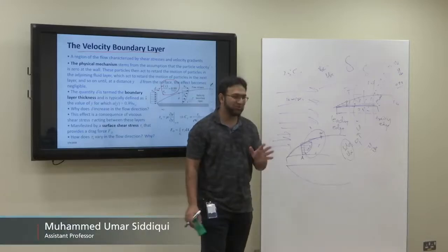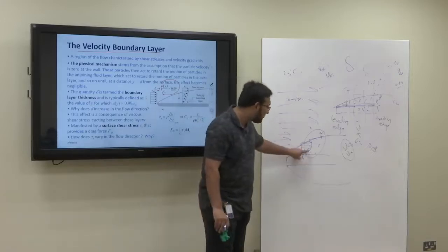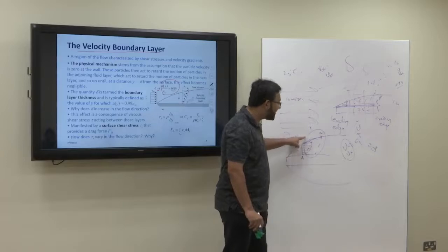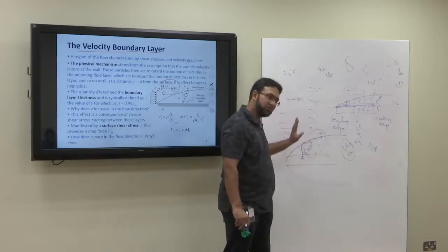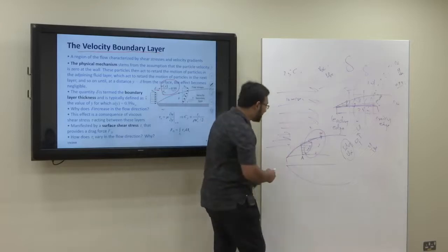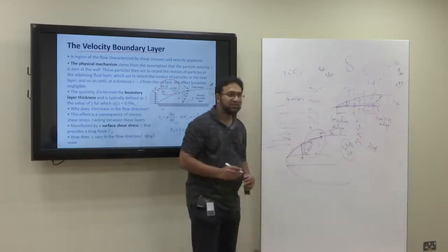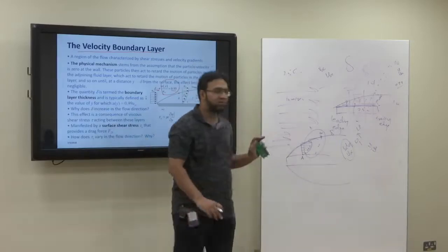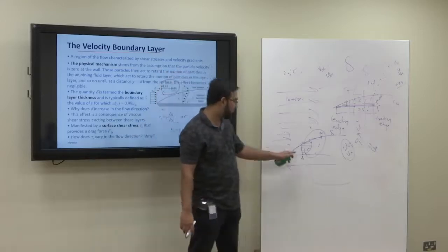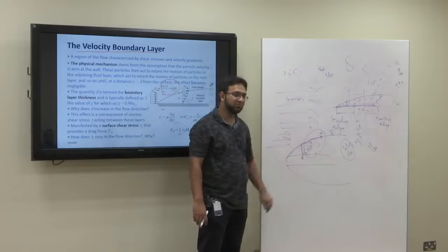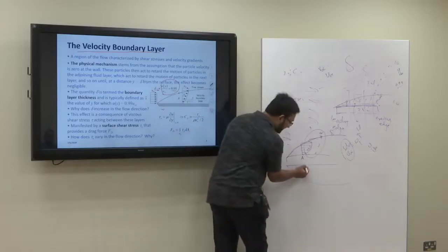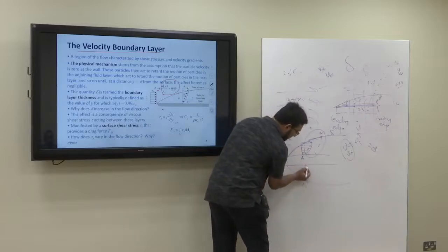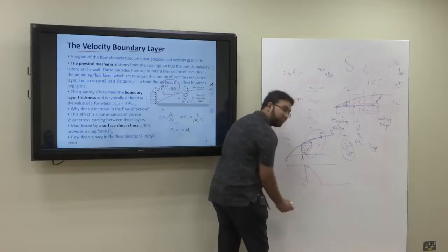First of all, do you understand? This is a velocity profile inside the boundary layer region. How do you know this is the boundary layer region? It's written here, delta. Delta means boundary layer thickness. So that's the boundary layer region, and this is the velocity profile. It starts from 0 and becomes maximum. If I want to draw it on the downside, then at this point it starts from 0, the flow is in this direction, so it should rise and become maximum.